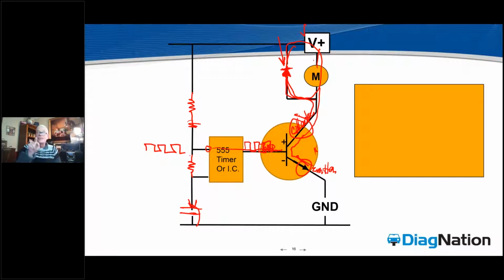Guys, this reflected energy is exactly what destroys every single PCM injector driver or ignition coil driver that you see go out in a module or a box. 95% of the time it's destroyed by this reflection process. And what's happened is the output device, or in the wiring, depending on where they have it, we've got a failure in that diode. We're going to be taking a look at a current waveform next to show you exactly how this works and how important this diode is in that pulse width modulated circuit for not wiping out your output devices in your PCM.